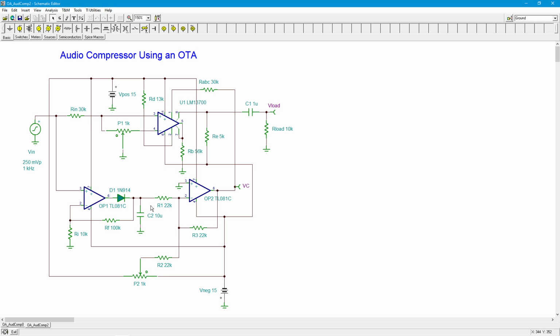If you're using this for a guitar and it's a purpose-built circuit, my suggestion right up front is breadboard the thing, try it, get the values that work best for you, and run with it. It doesn't really matter how well this works out on paper, how well it simulates. Ultimately what matters with these audio circuits, especially things like this or fuzz boxes and EQs, is how does it sound, right? What are your ears telling you? If it measures, quote unquote, great, but it sounds like crap, it's a useless circuit. What matters is how does it sound.